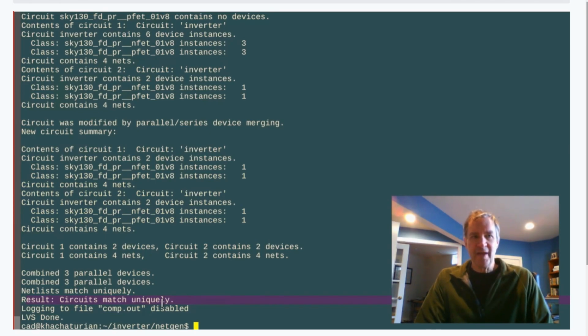If the layout is correct, then the last thing you'll want to do is to revalidate the circuit with a netlist derived from layout, including parasitics. Magic is not quite up to doing full RC extraction. It can do it, but there are issues with the method that require manual intervention, and which I plan to fix in the near future, so I will stick with capacitance extraction only for this exercise.